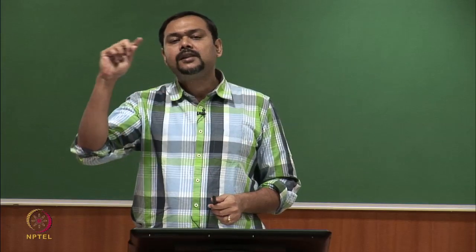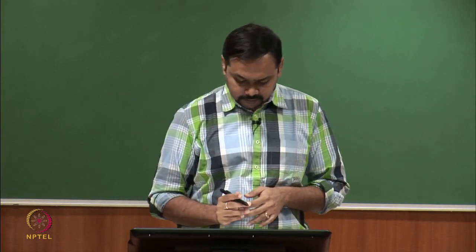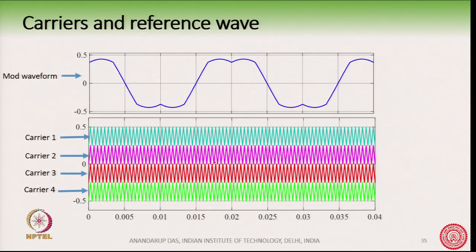The sine wave is continuously varying, and we need the pulse width modulation to mimic or produce this varying sine wave. So, wherever the modulating wave is present, the carrier should also be present, so that we can replicate the varying nature of the sine wave. Therefore, the carriers should span the entire height of the modulating waveform.